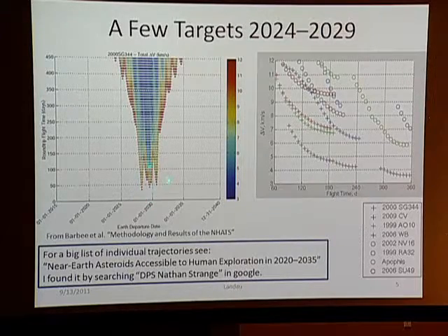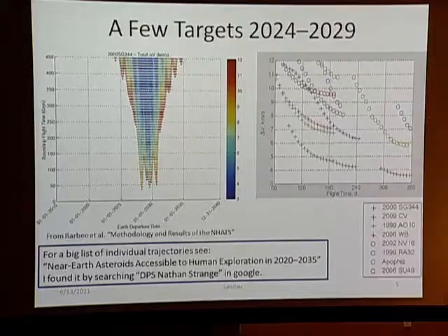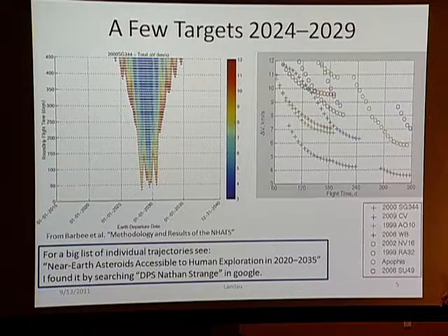So you see in the sweet spot of the launch window, you get the low delta V missions, which will help reduce the launch mass that you actually need. But it also gives you a clue, okay, do we have a long launch window in order to do this mission? How do things vary in terms of that? And doing that type of process, again, is not that computationally intensive. So you can basically just go through a four-dimensional grid in order to get this data.